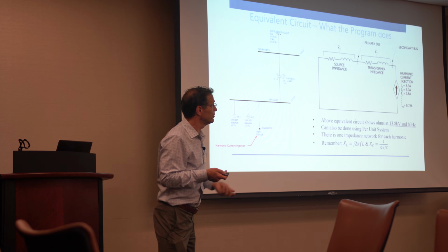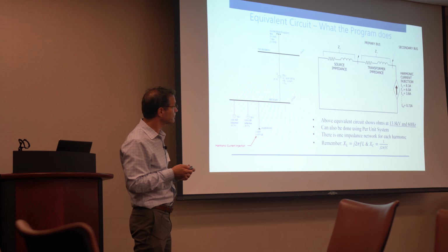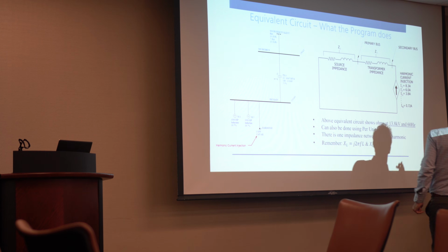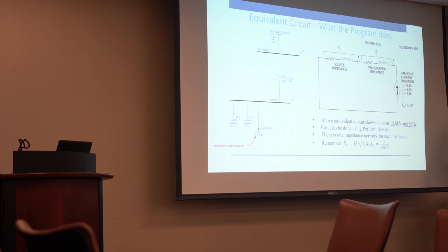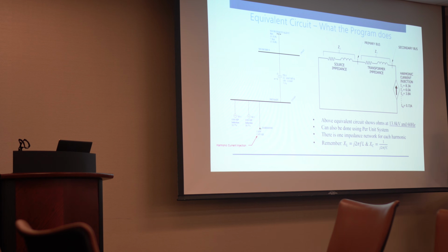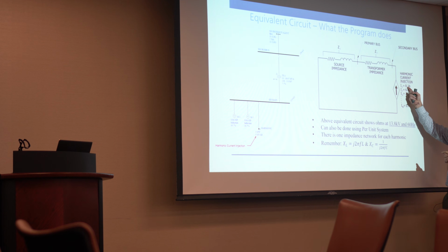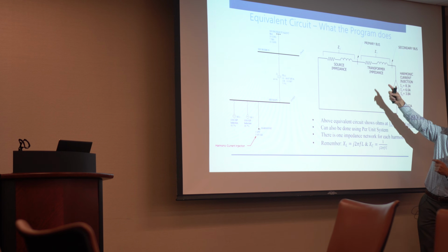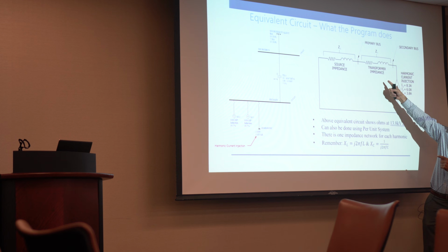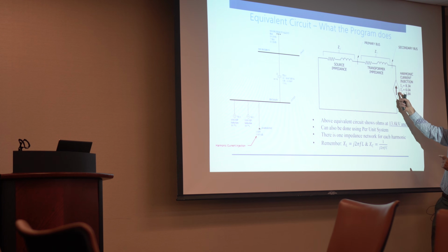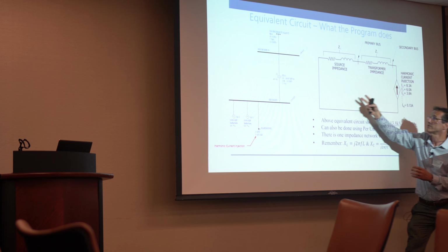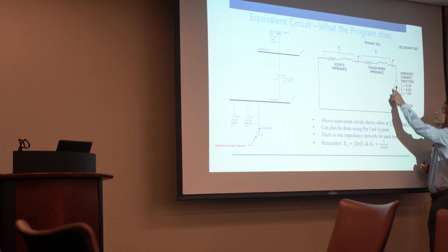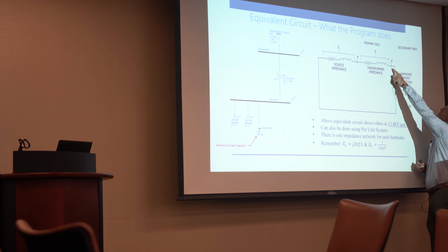In fact, we labeled it as an ideal current source here. What this means is that at the fifth harmonic, 5 times 60, 300 hertz, I'm injecting a current of 8.3 amps, and it's flowing into this impedance. So the equivalent circuit there is source impedance followed by transformer impedance down below, and then you have your current injection here. That's the very simple model. And if you think about it, if you want to know the voltage here at the 13.8 kV bus, that's what this is.